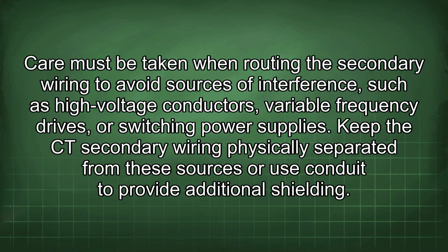Care must be taken when routing the secondary wiring to avoid sources of interference such as high voltage conductors, variable frequency drives, or switching power supplies. Keep the CT secondary wiring physically separated from these sources or use conduit to provide additional shielding.